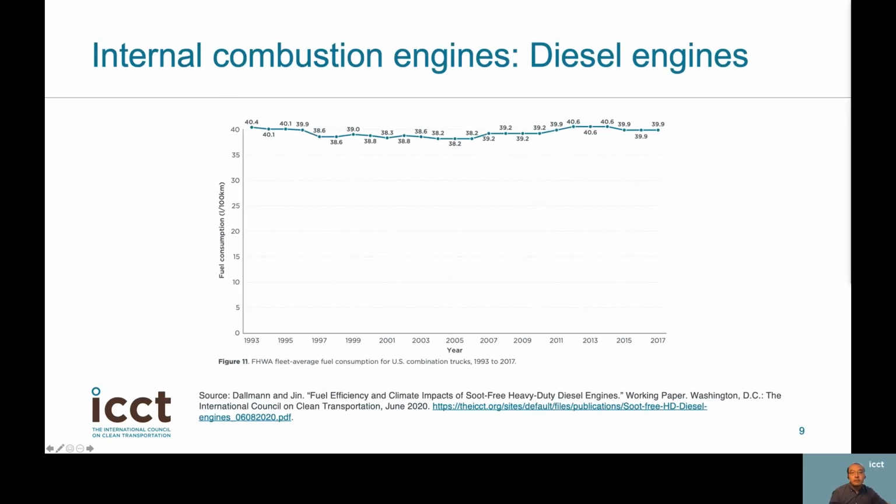While achieving unprecedented reduction in the pollutants they release to the atmosphere, Euro 6 or EPA 2010 soot-free diesel engines do not suffer fuel consumption penalties compared to engines that are only compatible with earlier emission standards. There is more variation within a single standard than there is across different standards, in fact. Manufacturers report even better fuel economy from their Euro 6 products than Euro 5 buses.